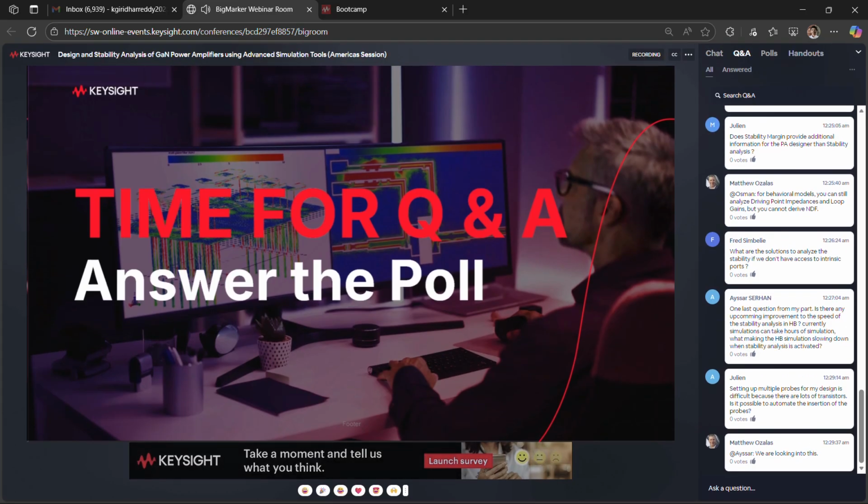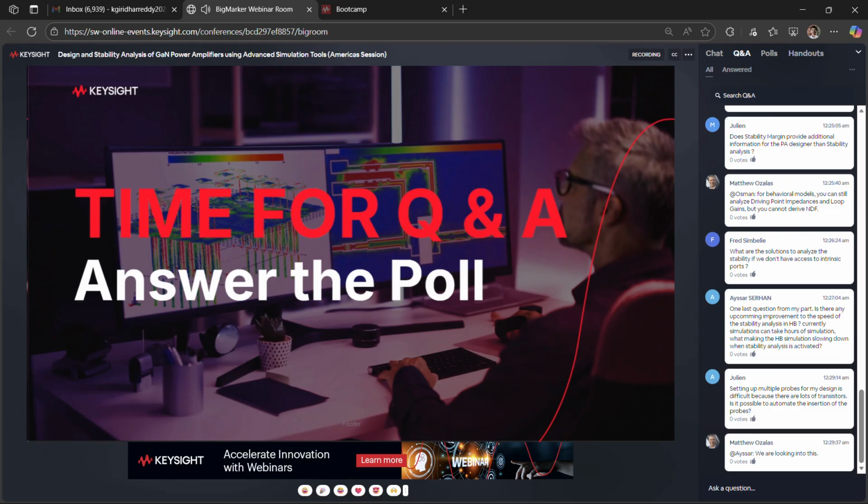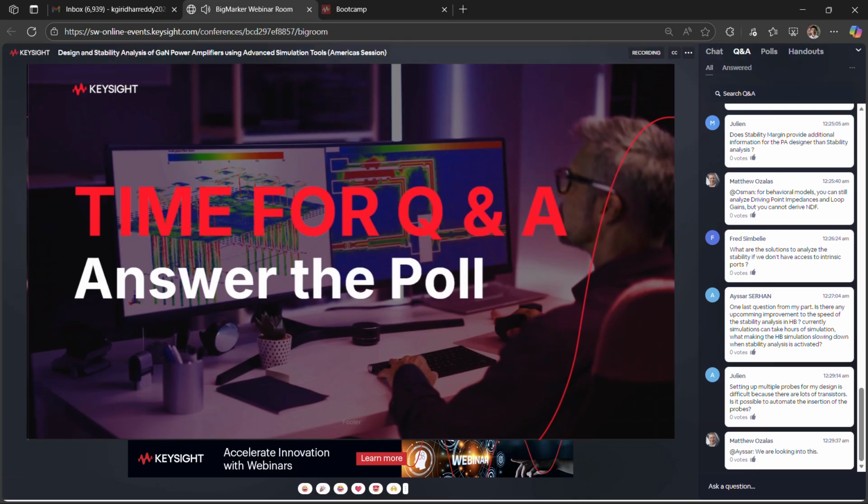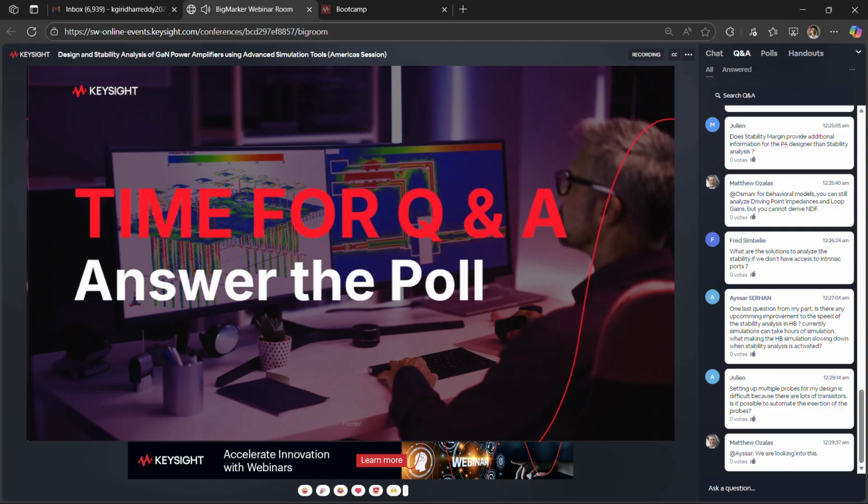You can also look more locally. So if you have multiple devices on a chip and they interact with one another, then that interaction can cause an additional delay in a feedback loop, and that delay could lead to a low frequency oscillation. That can certainly happen. And then we can even look at it across a single device. So if you have a single device, for example a very large device, well, you can have a temperature profile across that device that becomes unbalanced.